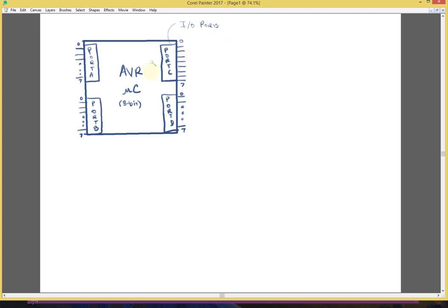It is the interface by which the microcontroller can control some physical device. For example, each I/O port has 8 pins, typically grouped in groups of 8 bits, and each pin emits a voltage level of 0 volts or 3.3 volts or 5 volts, depending on the logic level of the device. And then you use that to control a device.